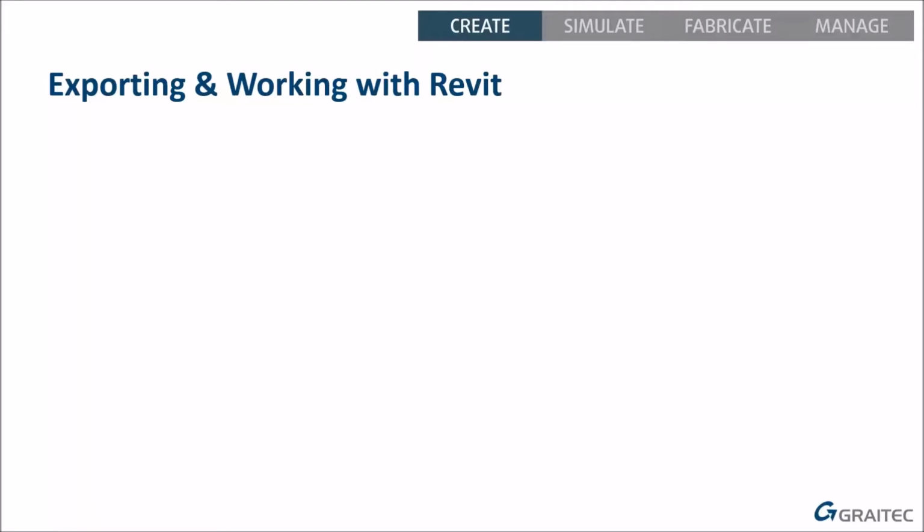We are going to look at it. One of my colleagues has done another webinar on working with coordinates in the AEC collection. So in Revit, you've got 3 coordinate points. You have an internal origin, which is similar to our AutoCAD WCS. That's completely fixed. You can't even move that. Same as in AutoCAD, you can't move that.